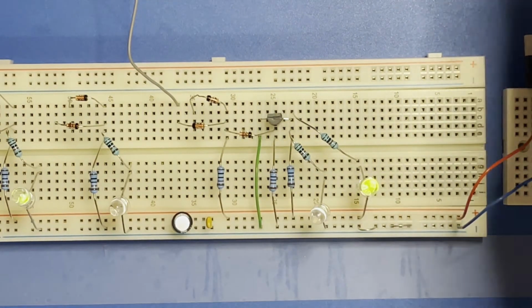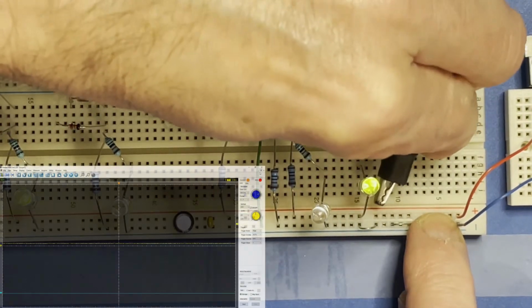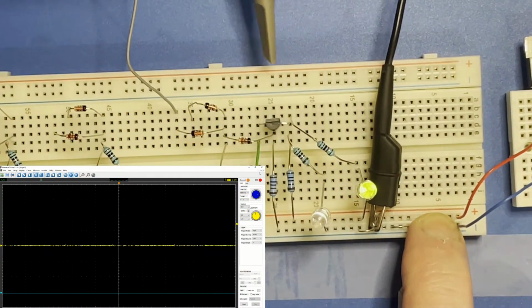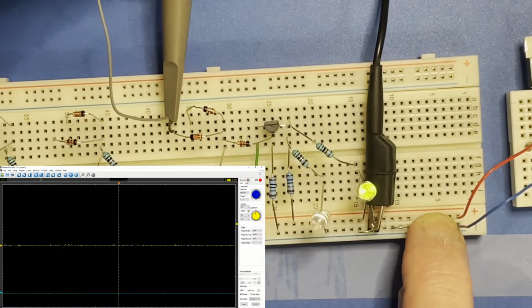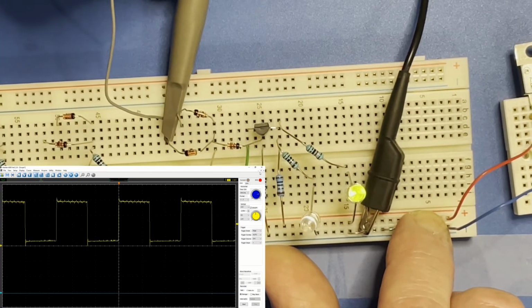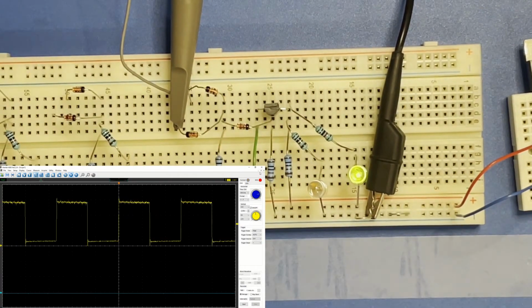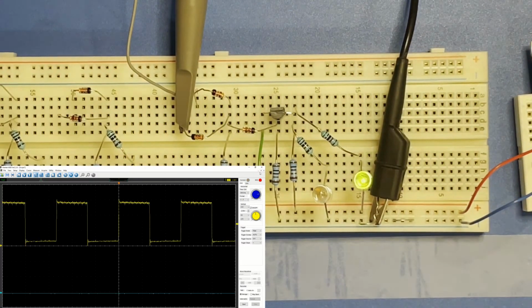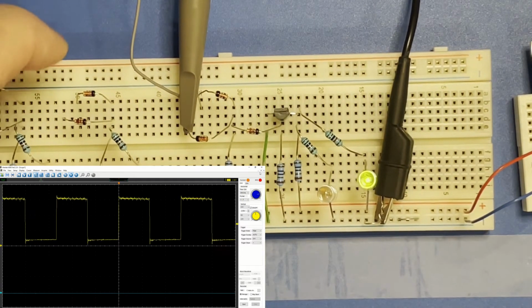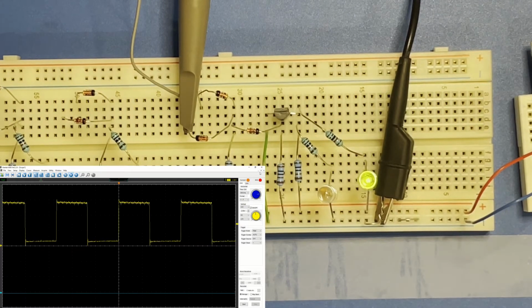So if I connect the oscilloscope probe here to ground and that input at the diode, and squeeze it through without pulling anything out too much. Right, so that's now showing a fairly noisy signal because, again, of the combination of the very long wire setup and loop using the breadboard. It's got a bit of noise on it, but having some noise is not at all unusual in practical logic circuits, as long as the noise levels are well clear of the thresholds of the gates.